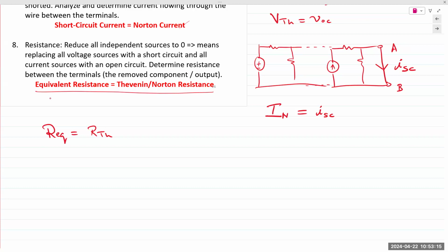And that's why all three circuits are different. The circuit for Thevenin resistance does not have any sources in it. Otherwise, you cannot find the total Req. So again, Thevenin resistance, no sources. Norton current, you have a short at the output terminals. Thevenin voltage, open circuit terminals. Any questions? Think over that. Let me know if you have any questions.